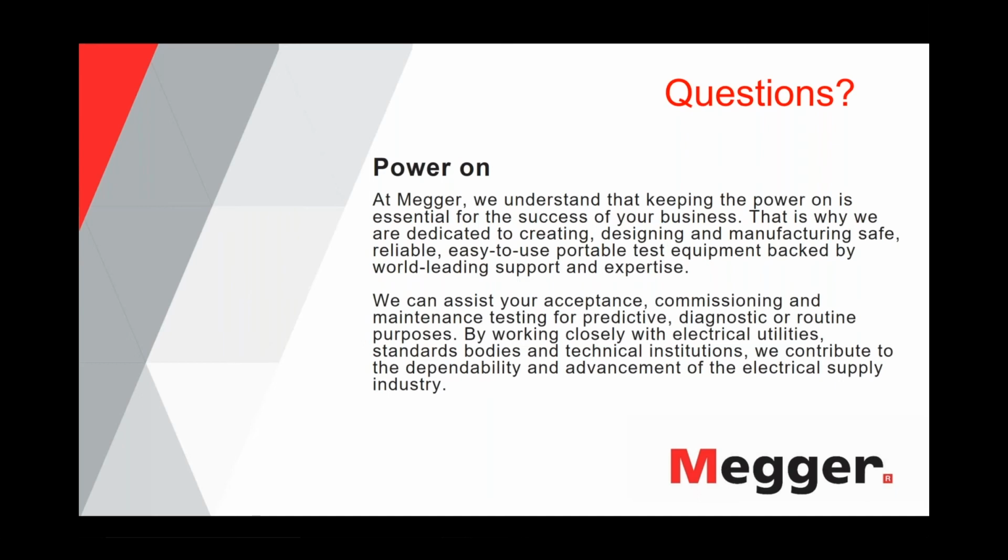You can put a special tape under the jacket, which basically, if the jacket gets punctured, would then absorb the moisture and not let it penetrate further into the cable. That is basically one prevention for getting moisture in.